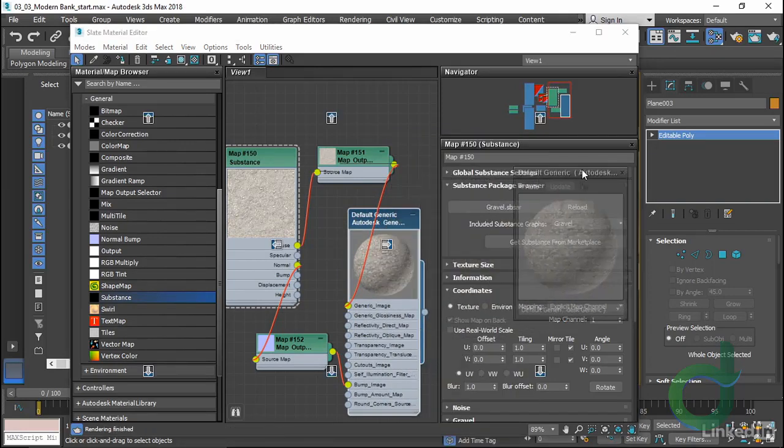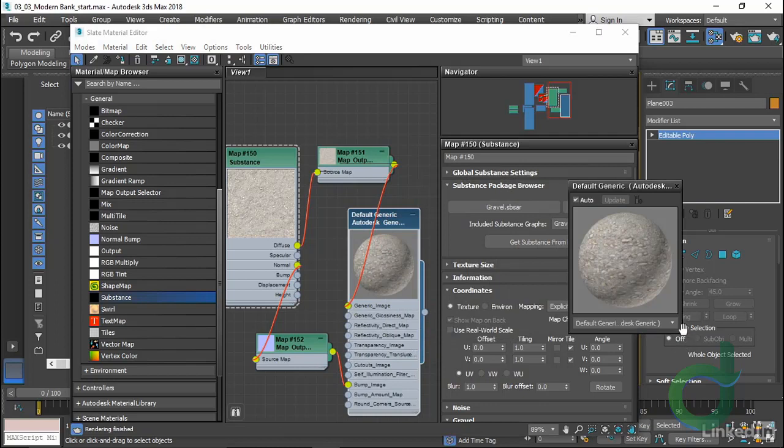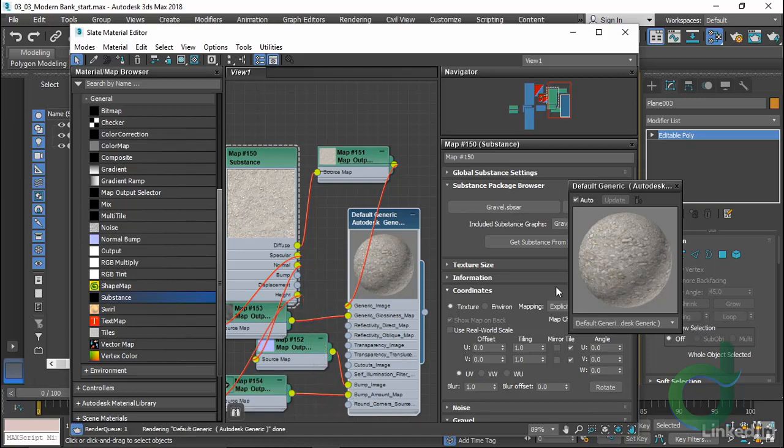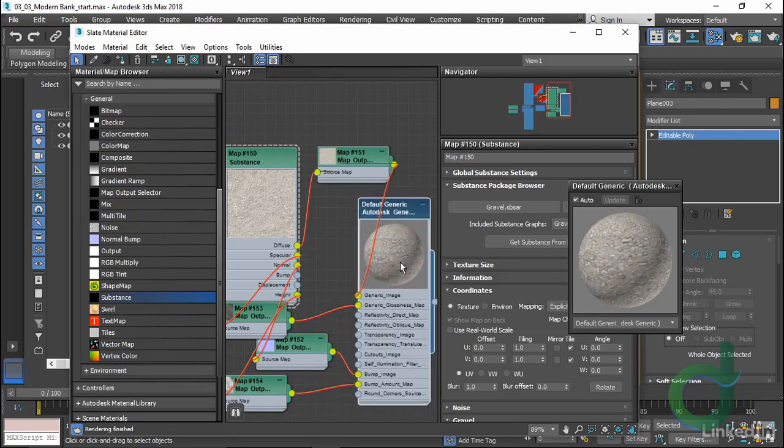Typically what I'll do is keep my preview window auto-updating. Then I'll start to bring in things like specular. We'll take specular over to glossiness, and finally height over to bump amount. This will give us an extra little lift on it, making it look a little bit taller, more vibrant. If you'd like, you can also bring in displacement or bump, but I'm going to leave those alone for the moment. There's no transparency or reflectivity we need at the moment, as it's a fairly matte surface.